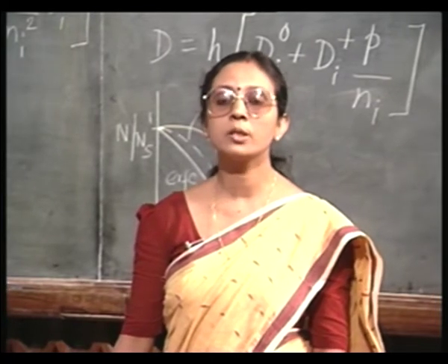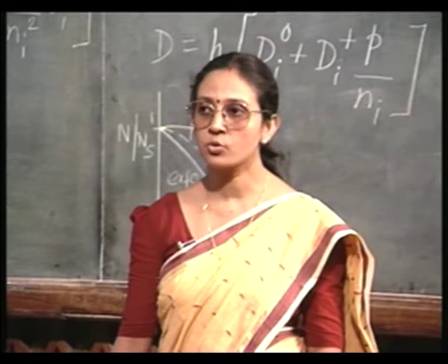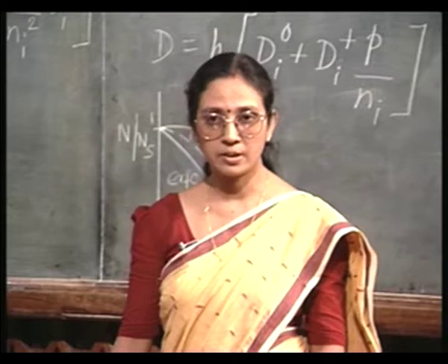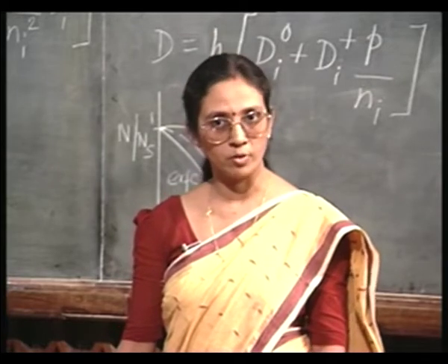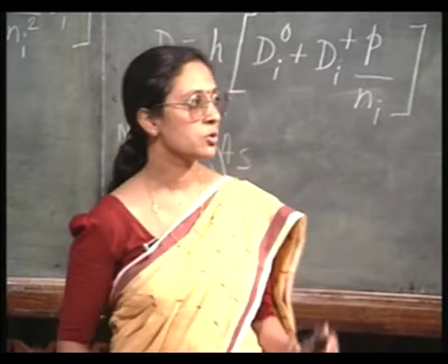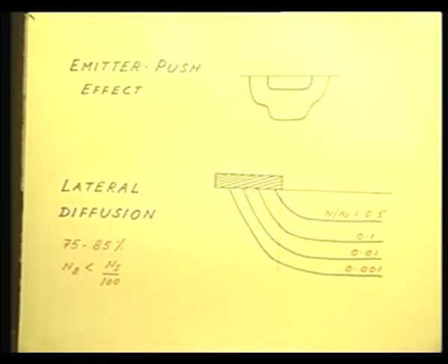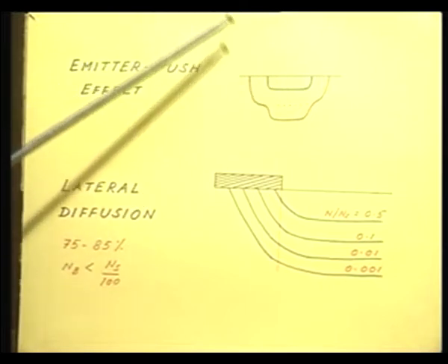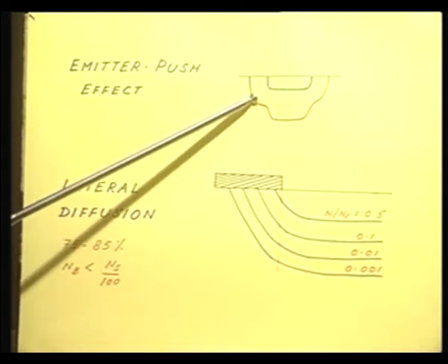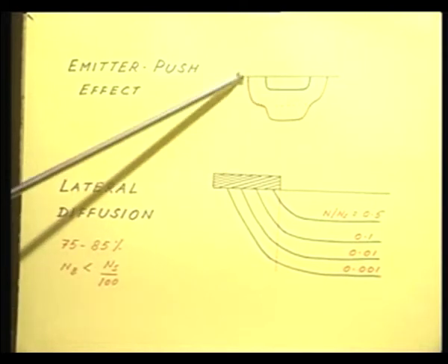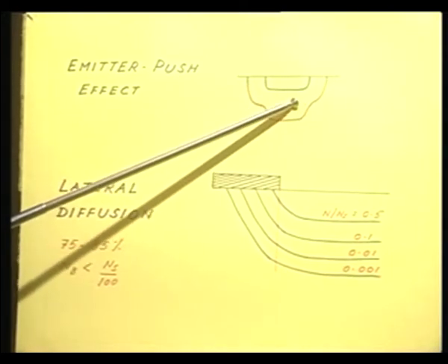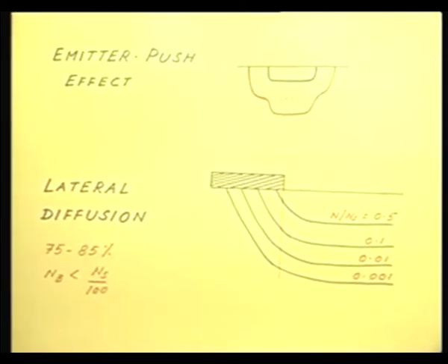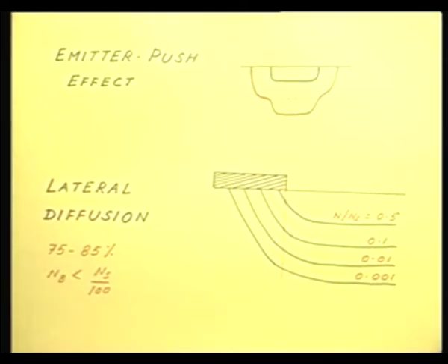So, when we are doing the emitter diffusion, the base should also get further deeper diffused, but this deep diffusion should be uniform, right. That is to say, what we expect is this green boundary is my emitter, and the base should have been given by this red solid and then the red dotted line. That is, it should have got deeper diffused all round the emitter, isn't it?